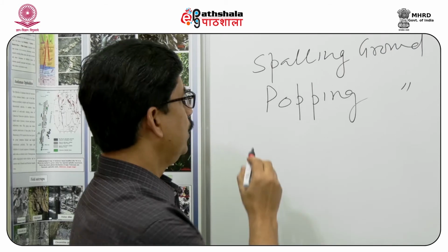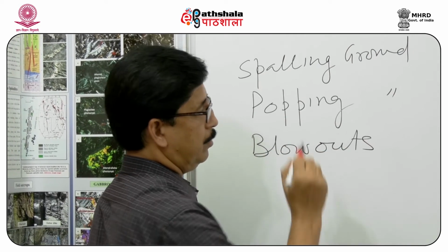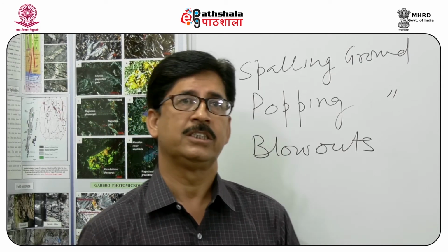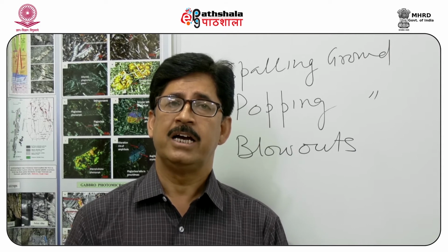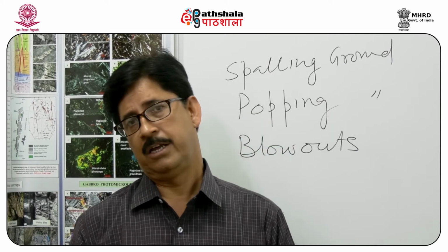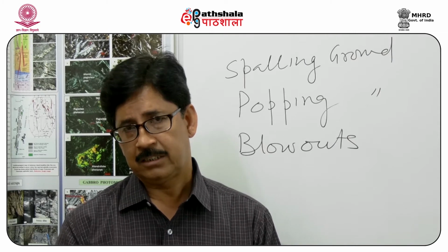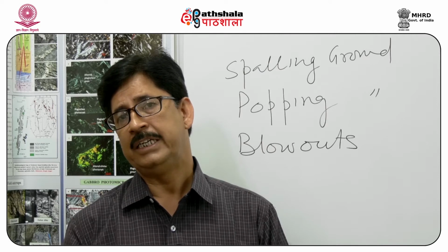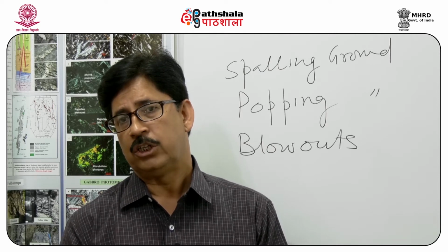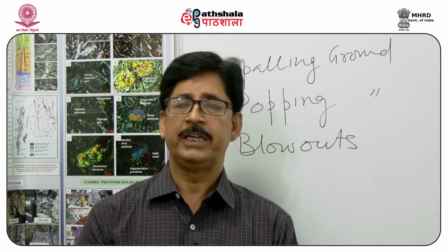We can have issues of blowouts, because the rocks in which excavation is made are sometimes under high stress. So when we create an opening, those stresses start getting activated, and this results in the generation of very small magnitude earthquakes because of breaking of rocks.